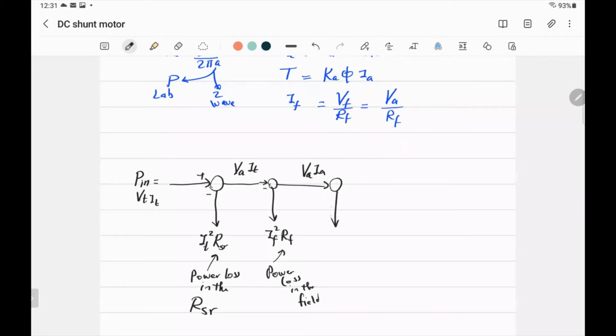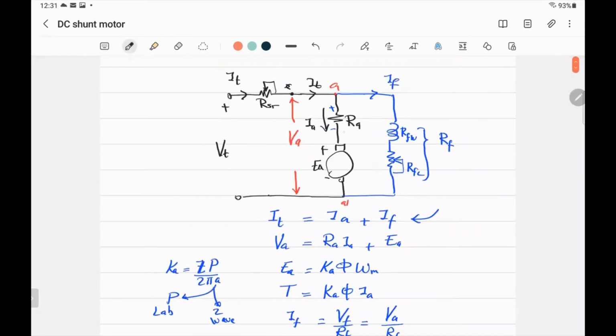And then there is loss here. If you subtract the loss in the armature resistance, RA IA squared, what's left? The developed power, the one that you want to take and convert to mechanical. That's what I need to reach. So let's subtract IA squared times RA.